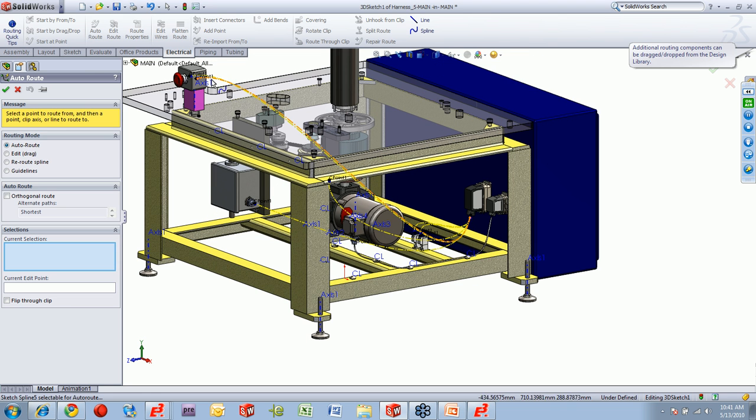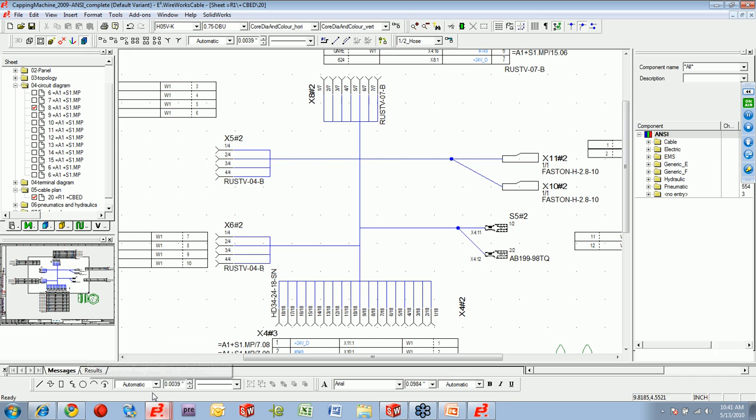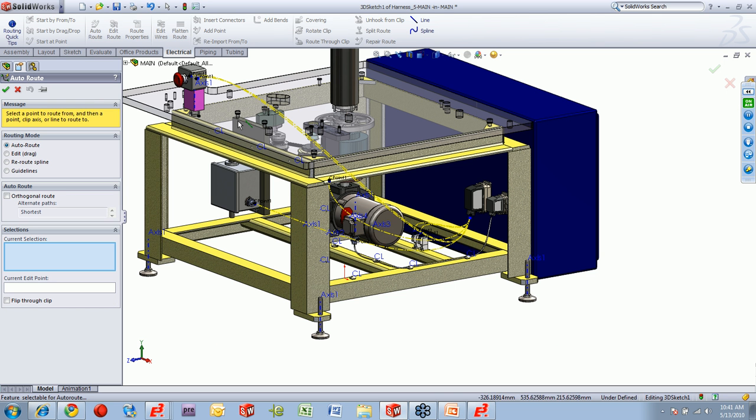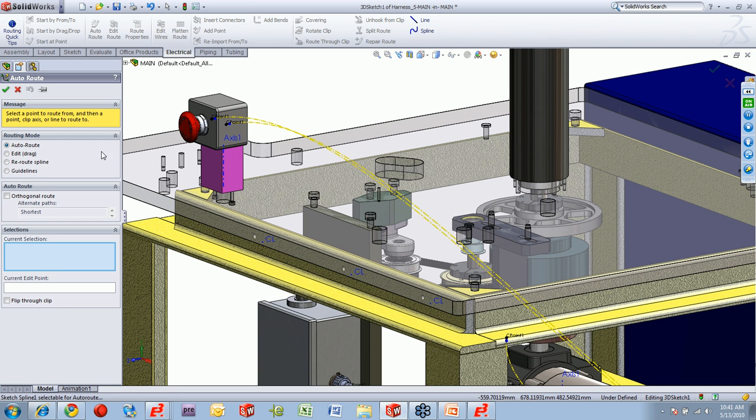So all of these yellow dotted lines correspond directly with all of these logical lines between the connectors. Okay, so we're already seeing some correlation between them, and that is what gets carried over. What we can do though is now use SolidWorks Routing to determine what sort of connection, or physical connection, we have between them.